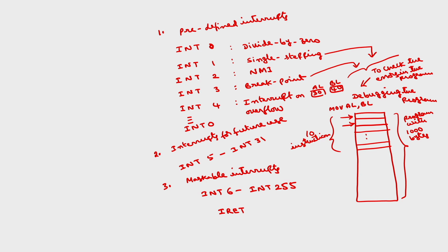The next group of instructions is the status instructions. They also use the implied addressing mode. In this case the operand is implied. For example, we have CLC, which stands for clear carry flag. Whenever this operation is executed, the carry flag will be reset. Similarly, we can clear the direction flag.